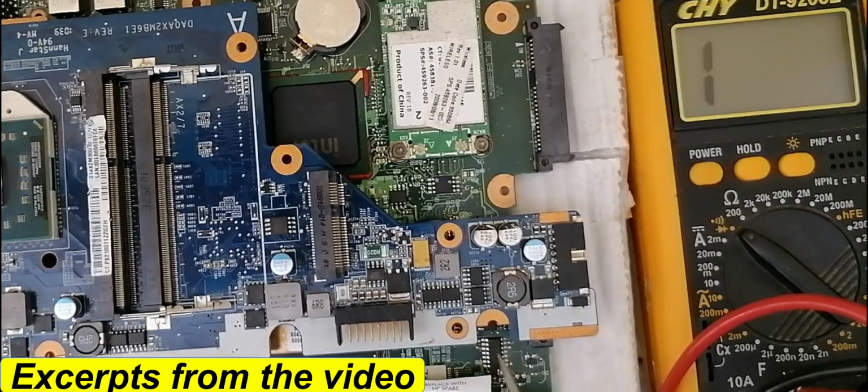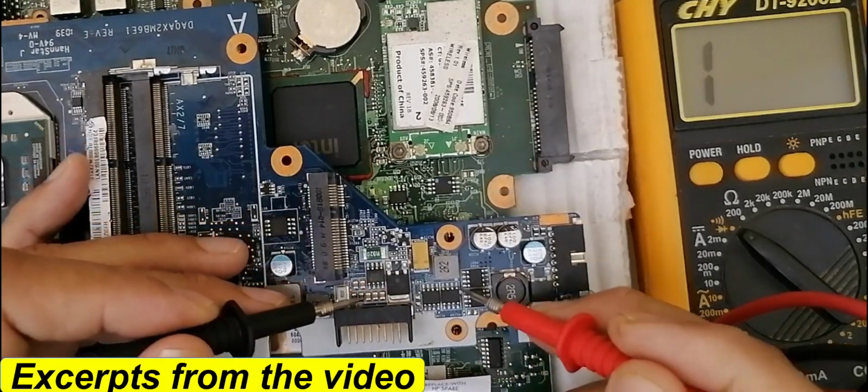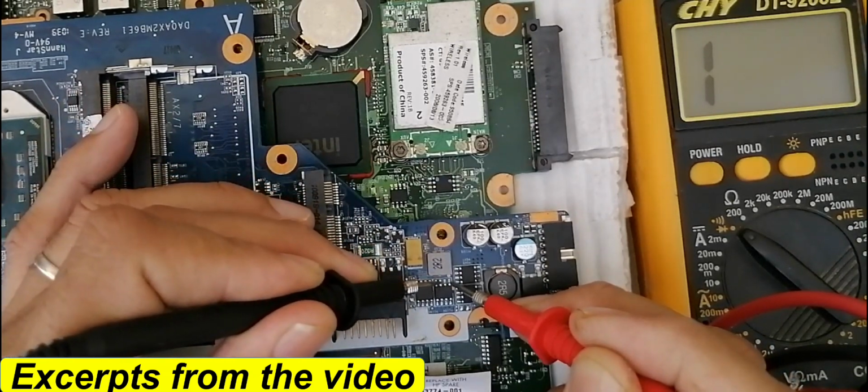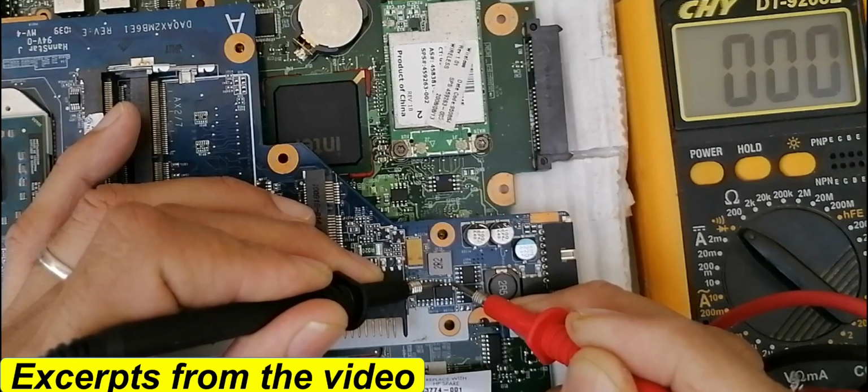Let's take this MOSFET. Do you see the white dot here? It means this is pin number 1, and pins 1, 2, 3 are source. We should find continuity here. So let's check. I will put one probe on pin number 1 and the other probe on pin number 2. We get continuity in the multimeter and a beep.